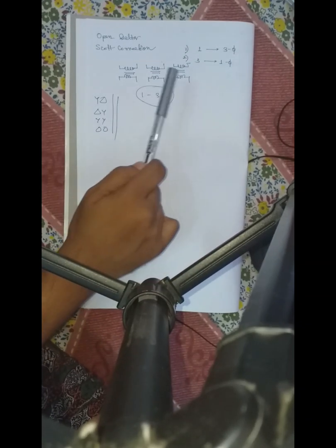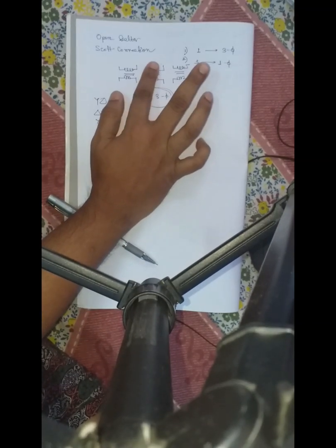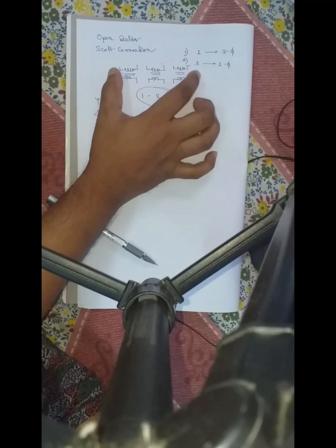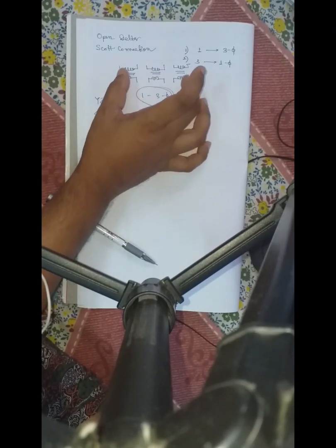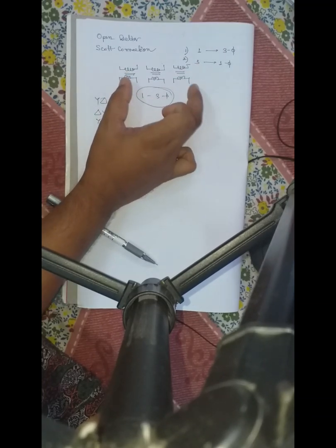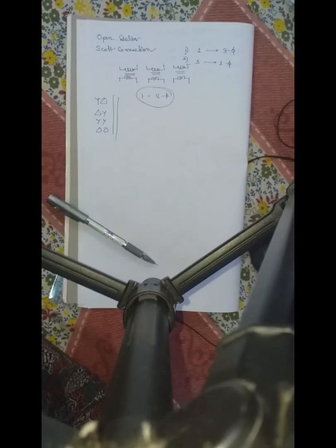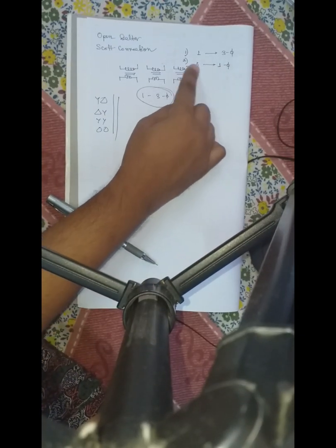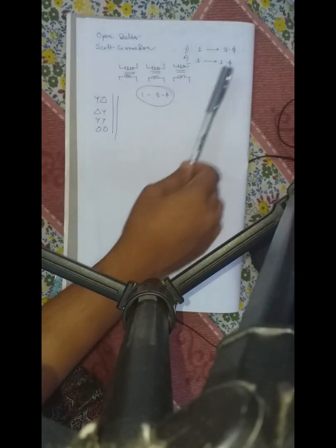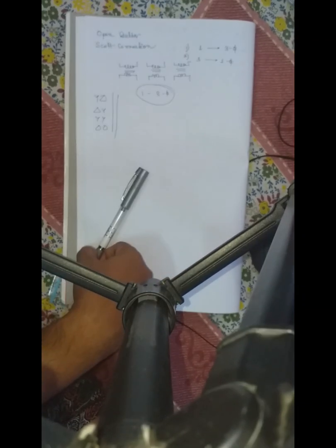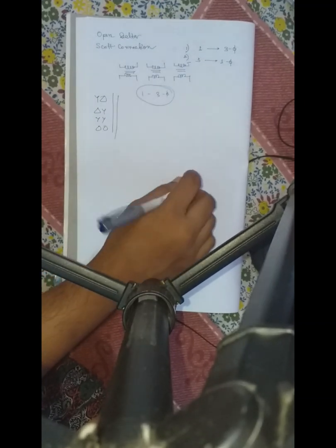The advantage of this type of design is that when one transformer is out for maintenance or for fault condition, two transformers are still available, so we can share the load using these two transformers. But with one three phase transformer, if one unit is damaged, we cannot operate using the other two units. A total shutdown will occur. So this is a benefit.